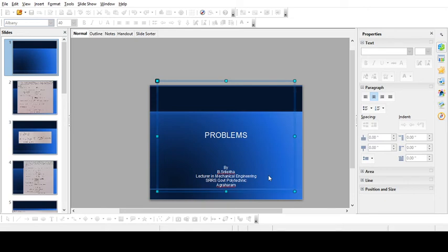So you can see in this particular problem that along its length it is 400 kilonewtons, and on the face of 250 by 100 it is 4 meganewtons, and on the face of 50 by 250 it is 2 meganewtons. Okay. Now, stress in the x direction, σ_x is equal to P by A. So in the x direction it is 400 kilonewtons and its cross sectional area is 50 by 100.